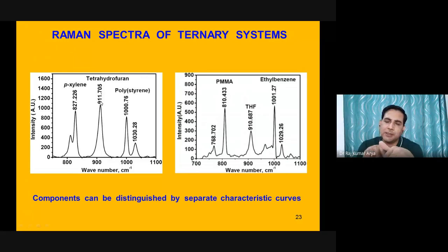So as you did, many people do actually for color, turbidity of your wastewater. So they put the sample in the photometer, they get the intensity of that particular UV light. Based on that, you are characterizing how much is the concentration. You are making a calibration curve. Same thing needs to be done here. Also, you are taking intensity and plotting it with respect to concentration there.